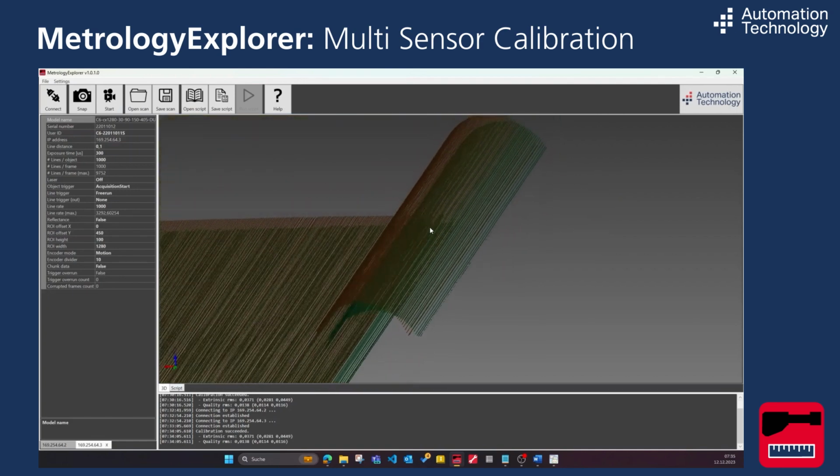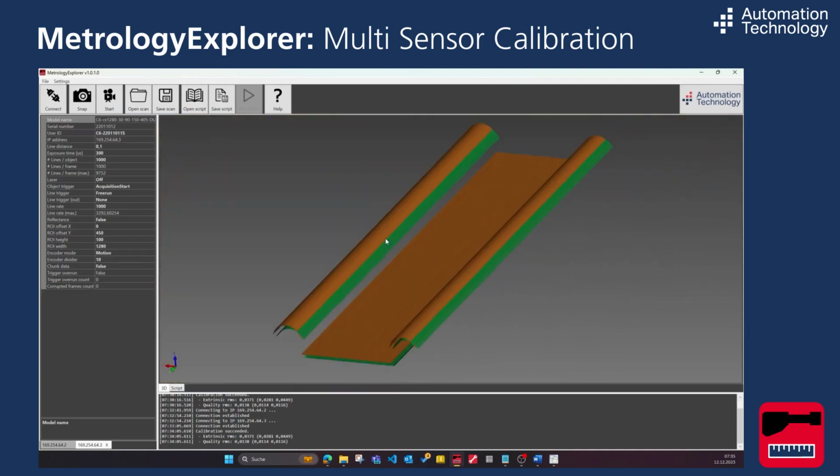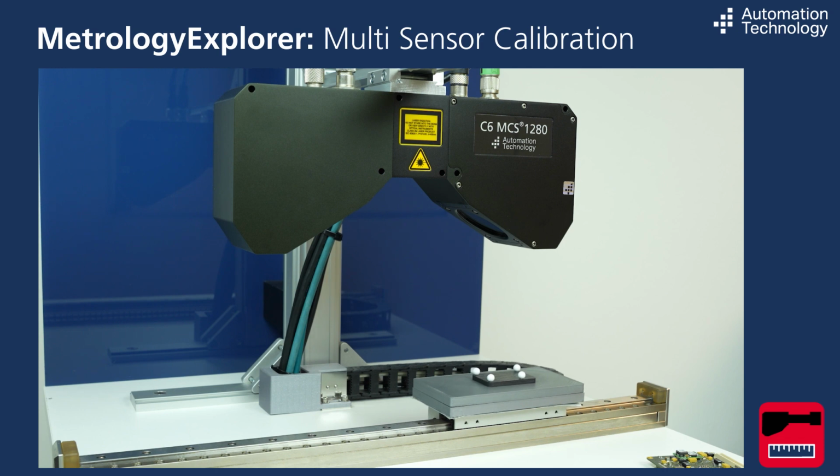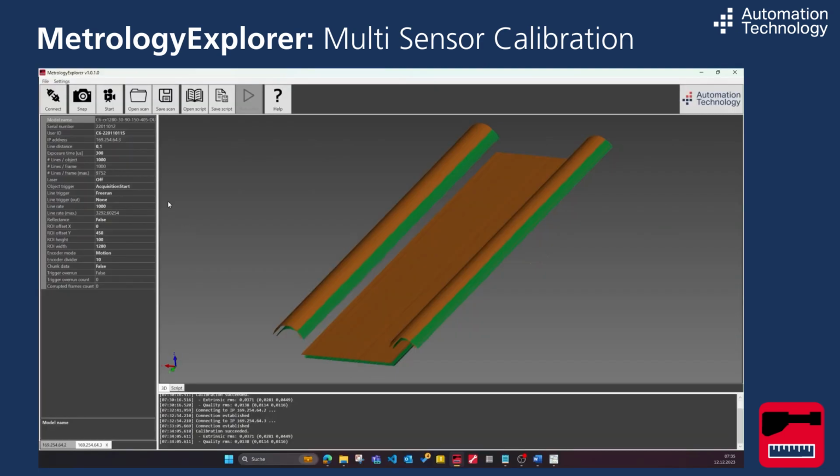The parameters will most likely need adjustments to the setup. In this case, we work with a linear axis, which supplies signals as a profile trigger via an encoder and outputs a digital output as a start trigger. We select In 1 for the object trigger and set the line trigger to encoder.